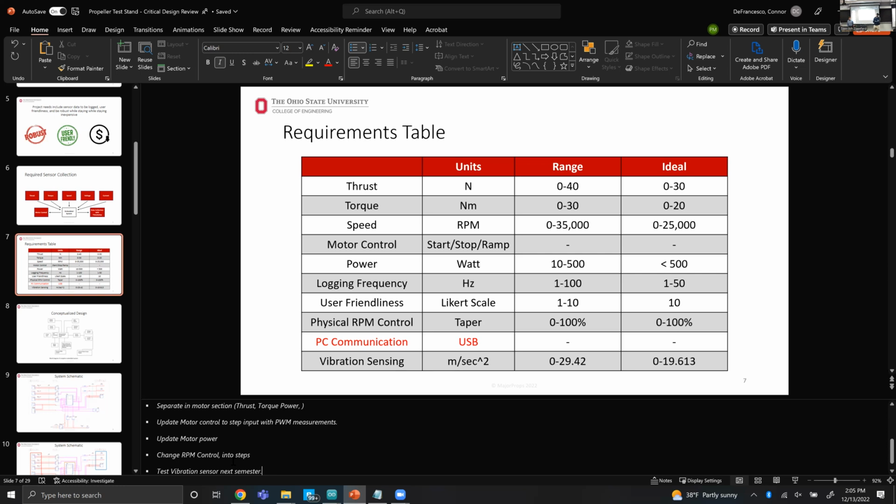We also had another issue with the footprint, which was a big issue. We didn't find that out until right before Thanksgiving. The footprint for the spring connector, we got it from Mouser, but it was wrong. The pins on it were somehow labeled incorrectly. The fact that you can troubleshoot and find the problem is a skill, like knowing where to start and where to look. So these are two things that now I know to check if someone asks, have you checked this? Have you checked that?